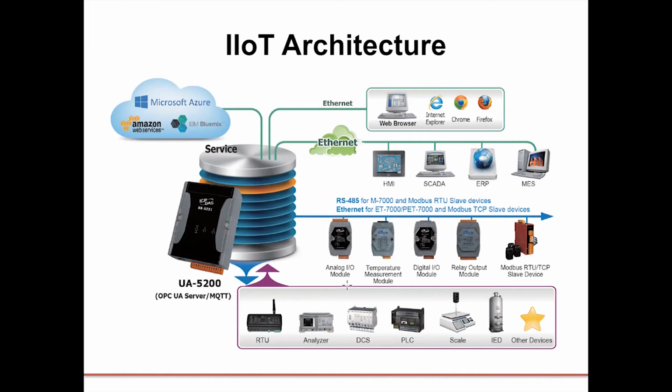This comes from the application of one of our OPC servers, the UA5231. This model is slightly out of date now, but I think it still provides a good example of how you can incorporate different networks and communication methods into the IoT platform. This model comes with 4 serial ports to connect a wide variety of devices, and it uses its Ethernet interface to push data to Ethernet controllers as well as to your cloud.